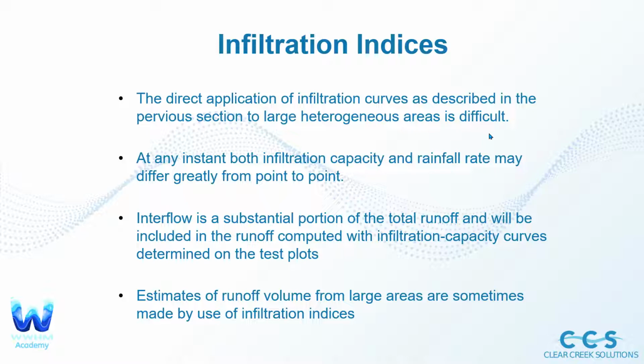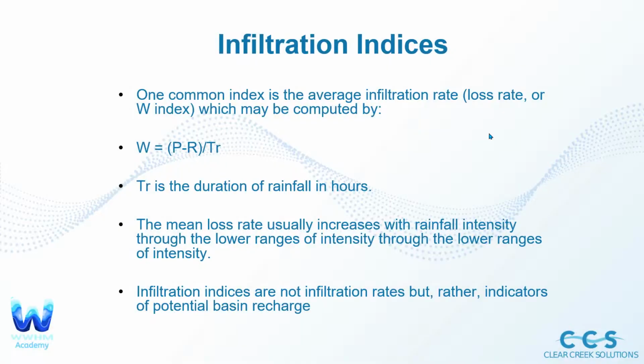And also, interflow is a substantial portion of the total runoff and will be included in the runoff computed with infiltration capacity curve determined on the test plot. So if we already have some interflow going on in the project site, that'll also factor into the infiltration capacity curves and skew the result a little bit. So estimates of runoff volume from large areas are sometimes made by use of infiltration indices.